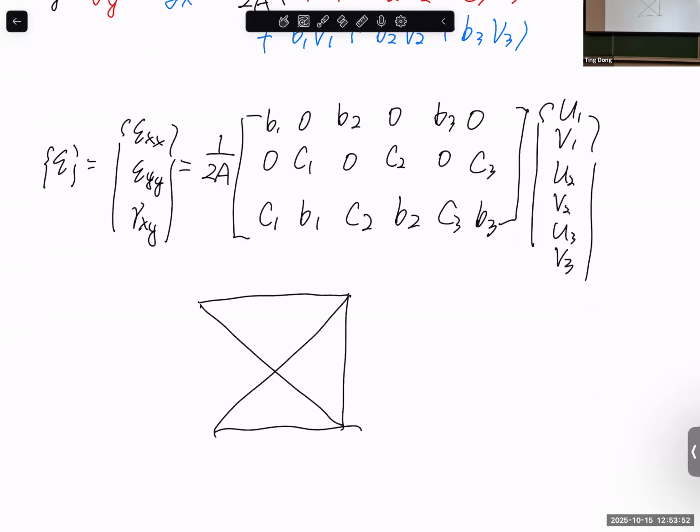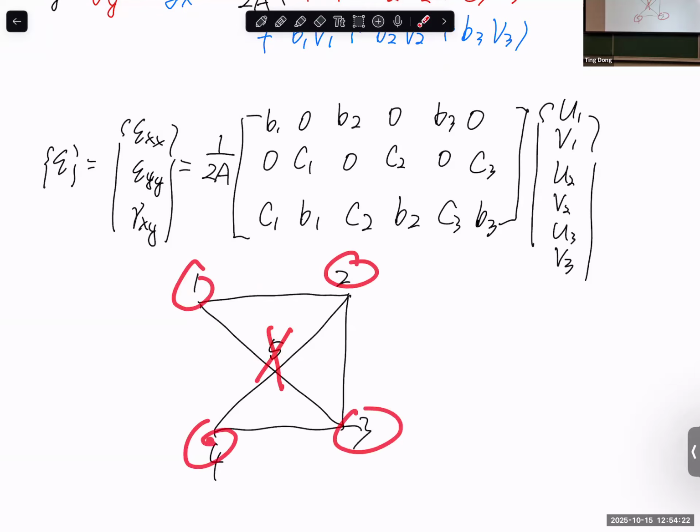So basically, we had 1, 2, 3, 4, 5. And the input file generated from Abaqus, after you draw this sketch in Abaqus, has the definition: node 1, x coordinate, y coordinate, node 2, x coordinate, and node 5, all 5 of them, right? So in that definition, you need to remove this node. So basically, you keep 1, 2, 3, 4. And this is the node definition.